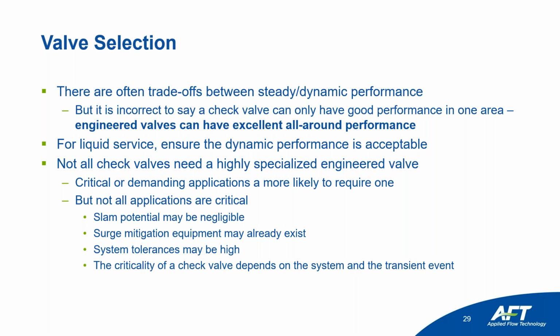However, we would say the second bullet point here, if you are running a check valve in a liquid service and it may slam, you should always check to see that your assumption is okay. Don't just look at it and say, yeah, this is not a critical application, we don't need to do any analysis. You could really get yourself in hot water doing that.